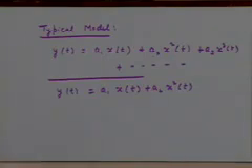Now how does this distortion differ from the linear distortion that we have discussed? In one very, very important and very significant way. If you remember, I had made a comment when we talked about linear distortion, that linear distortion which arises due to non-ideal characteristics of the channel in terms of its transfer function can only do something good or something bad relatively to different frequency components that exist in the message signal, right. But it cannot create additional frequency components, isn't it? A linear filter essentially affects whatever frequency components are present in the message signal.